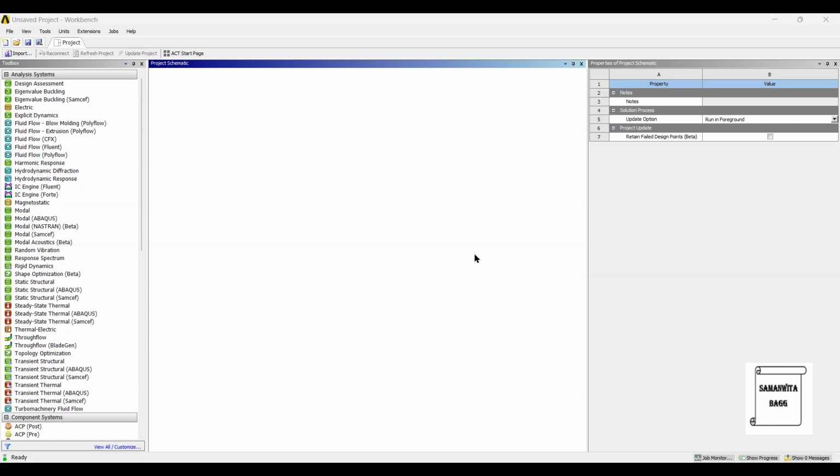In this session, we are going to analyze a D-type anchor shackle for its modal analysis. We will figure out the natural frequencies of the shackle at which it will show a particular amount of deformation and vibration which could be harmful for the shackle. So we will want to know what that frequency is that we need to avoid resonating our body with.